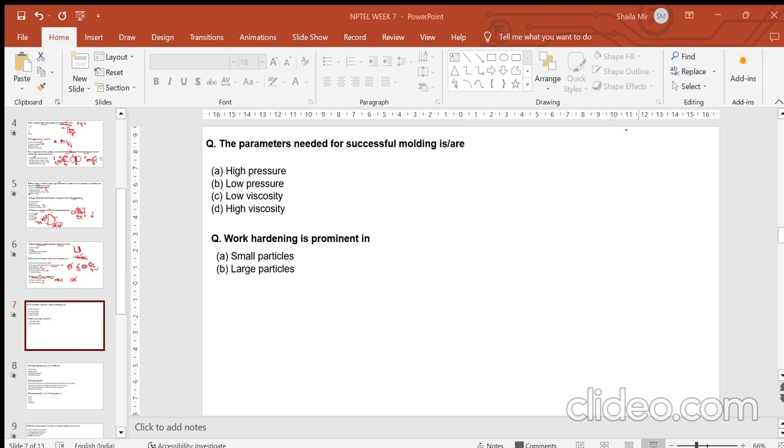This x by d is actually the H by D factor. You might have covered this in your classes. If you have a higher H by D, you will always have a lower pressure. So here, because we have a high compaction pressure, the H by D ratio will decrease. Just based on your equation, you can conclude this, right?